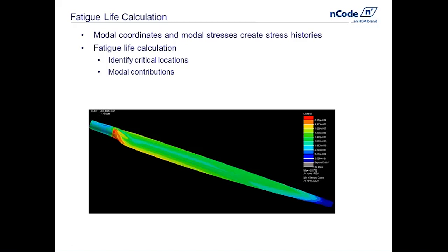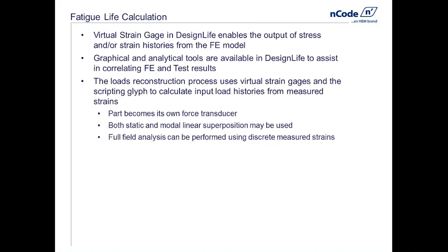And with those recomputed load histories along with the FE results, static or modal stresses, I can do a full model analysis in terms of fatigue, which is what we did in this particular case here. Again, what we're virtually doing here is turning our part into its own force transducer and using that to recompute the forces that would have been applied.